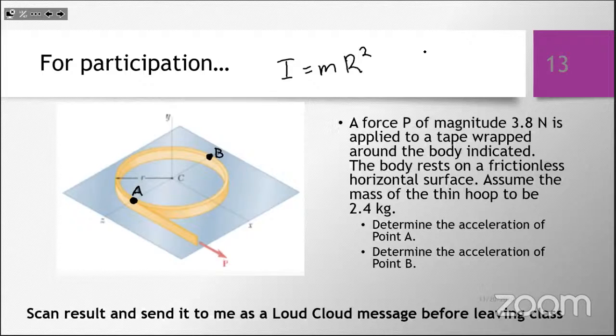Well, what are we being asked for? We're asked for accelerations, right? Think back to class on Wednesday. I had that flow chart up here with the three categories of problems. Impulse and momentum: if you're asked for velocity or time, look for impulse momentum. If you're asked for forces, distances, or velocities, that's work and energy. And when you're asked for forces and accelerations, that's Newton's law. So which one does this fall into? It's Newton's law, so we should be able to use it here.